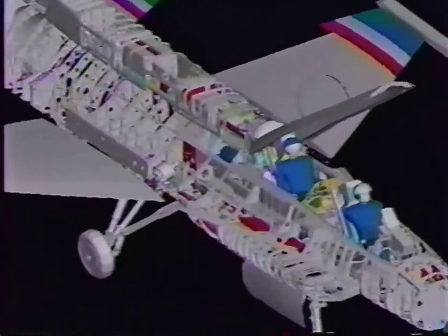The right-hand console was selected for the disk drive cartridge, allowing quick access prior to or possibly during each flight. This component provides the flight characteristics of the simulated aircraft. The aft equipment bay is used for the installation of VSS, instrumentation, and production equipment because of the easy access it provides. The Raymond Disk Electronics Unit installation is located to be near the disk drive cartridge in the crew station. Space in the center of the bay has been provided for a provisional Kaiser reconfigurable display processor, which controls a variety of cockpit displays.